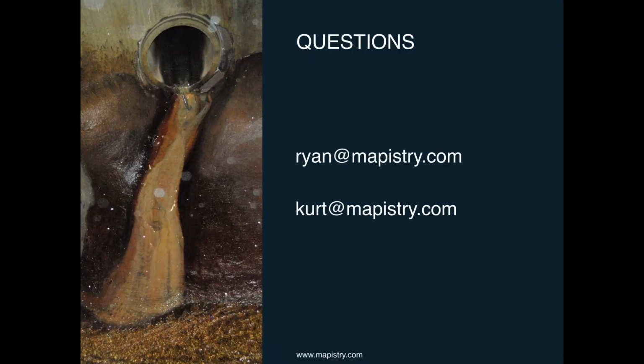Can you give some examples of BMPs that you've seen, that you've had success with, for dealing with copper or zinc on industrial sites? Somewhat. I've been up in the Pacific Northwest and in Washington State, so we've had our industrial permit going for a while here, where permittees can get into the level where they need treatment. On the extreme end is often electrocoagulation or chemical flocculation, say with a chitosan chemical that causes things to flock together.